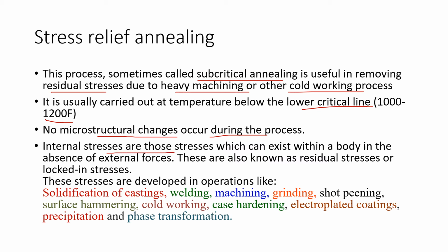Internal stresses are those stresses which can exist within a body in the absence of external forces. These are also known as residual stresses, or locked-in stresses. These stresses are developed in operations like solidification of castings, welding, machining, grinding, shot peening, surface hammering, cold working, case hardening, electroplated coatings, precipitation, and phase transformation.